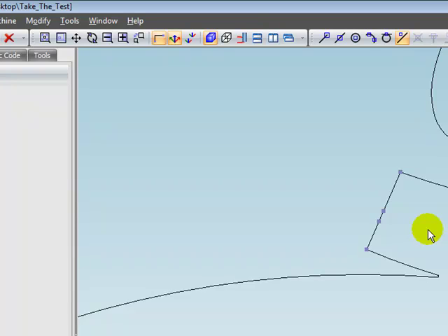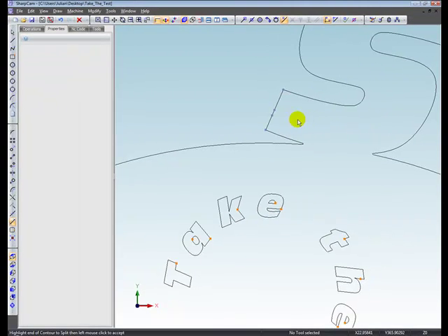Sometimes you choose the select all command and connect everything. But if there was an ambiguity where more than one endpoint of an element's met, say two or three elements met at the same point, it may have gone off in the wrong direction, because the order that it connects in is the order that the contours were created in or imported in, so it might not have been right. So you may need to go back in and split the contour and then reconnect in the desired order.